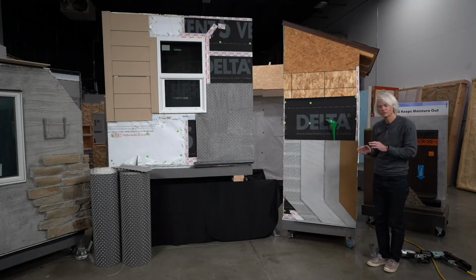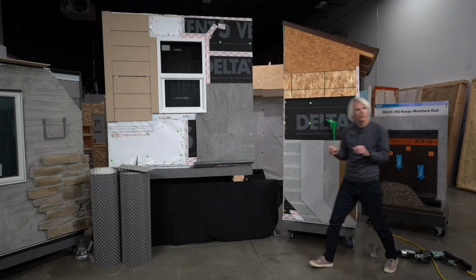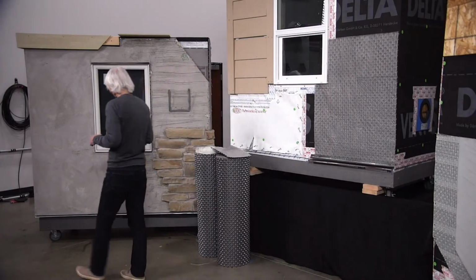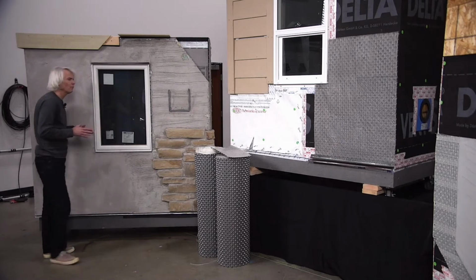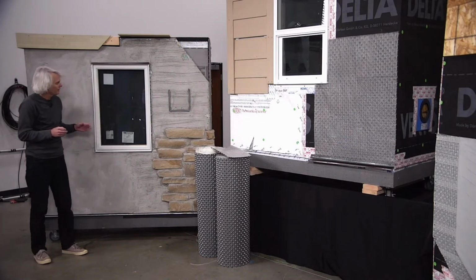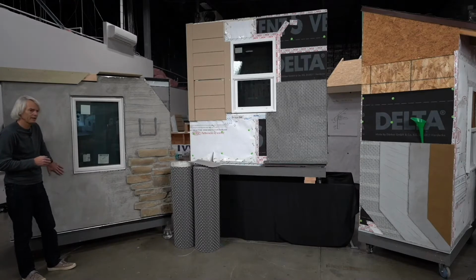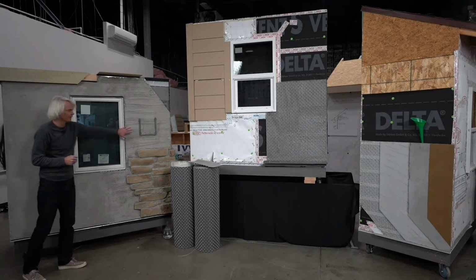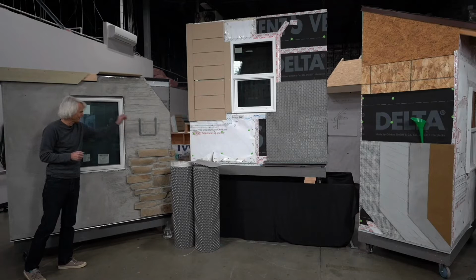Now, what I want to do is take this same product and a few other ones and look at some of the other critical detail areas that we have on the building. And so now we've constructed yet another mock-up here at CI Live, and behind me I've got a brown coat, so the second coat of a 3-coat stucco system, and over here we've got the scratch coat. You can see the lines etched into it, and we've adhered some stone on the bottom portion of the wall.